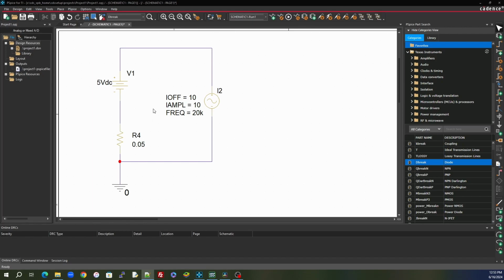And then for my load that I'm going to put on the system, like I said, if it's a brushless design, you're going to be pulsing it. So we're really concerned about pulsing currents on this one. If it's a static heavy current load, you're going to see the same effect, but it's going to be constant, right? So you've got to solve it in a different way.